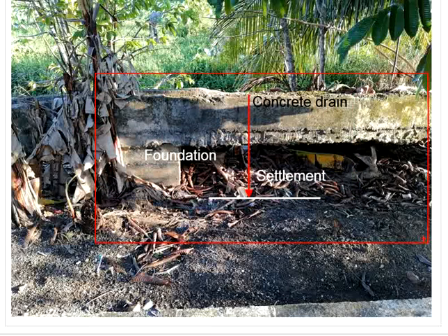This is another example here. This is the concrete drain. The foundation is here, and this is the total settlement after 7 to 8 years. You will see that ultimately the drain cannot function to discharge the water. This will become redundant. In the case of runoff, the water will go elsewhere without following the designated drain, and the entire drainage system is not effective.